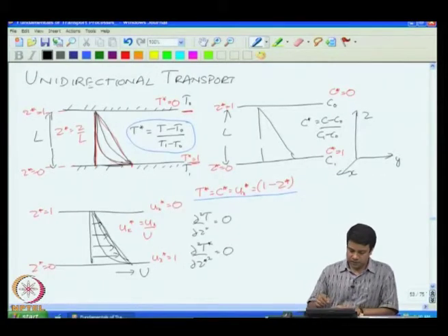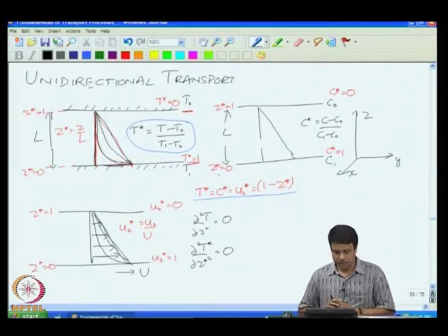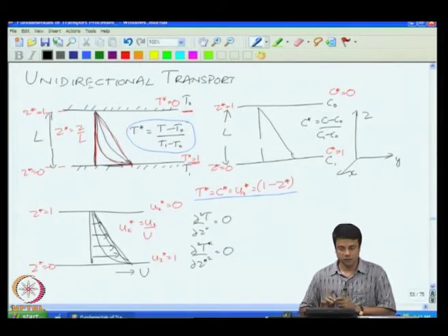And the steady profiles were exactly the same when expressed in terms of the scaled temperature, concentration and velocity fields, k 1 minus z. So, having got the steady state solutions: you keep two surfaces at two different temperatures, what is the temperature variation in between? Two surfaces at two different concentrations, what is the concentration variation in between? Two surfaces moving with different velocities, what is the velocity variation in between? At steady state, they have exactly the same form. That is because the equations of motion that we got in all three cases are exactly of the same form.